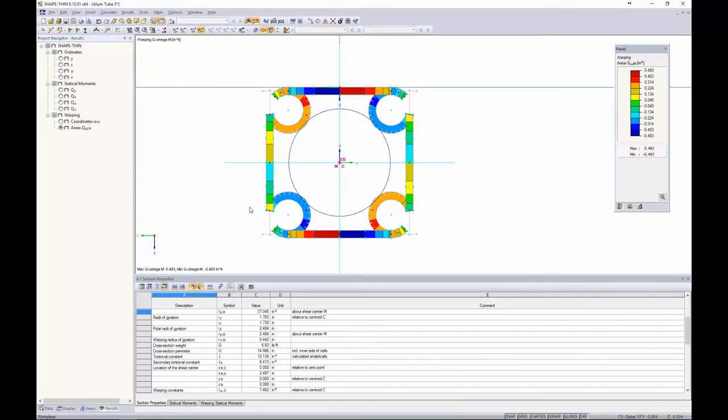And that's because I need to implement these C sub T elements within ShapeThin. And C sub T elements are just width to thickness ratios. Now, in order to implement C sub T elements, they can only be added to these straight line segments here. They cannot be added to these arcs. So if I was concerned with local buckling of one of these arcs, or had some other different shape where I had a rather large arc that I'd like to check local buckling, then it's suggested that you create multiple straight lines that compose that arc, and then you can create the C sub T elements.